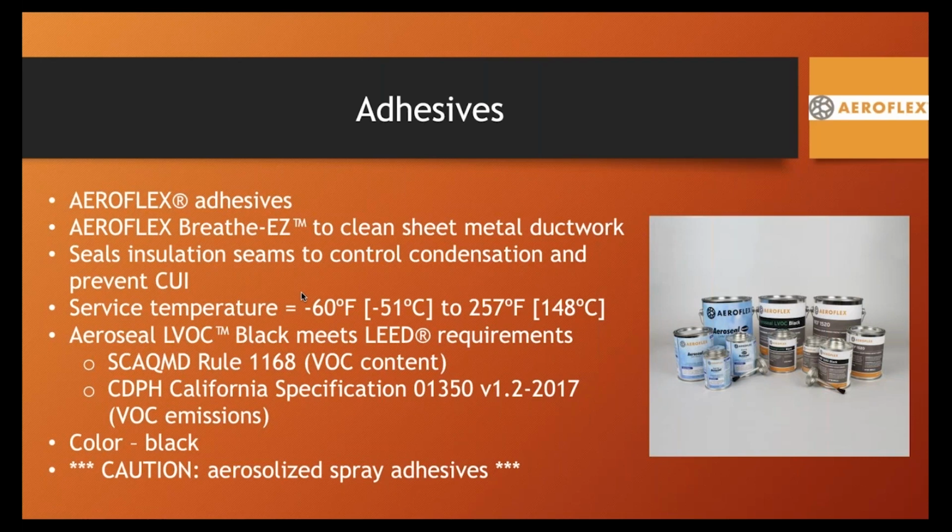have a favorite low VOC, typically spray adhesive, that they use for their fiberglass liner, and it's water-based. The problem with using water-based with elastomeric is that water gets trapped between two impervious surfaces, the sheet metal and the elastomeric liner. So it takes forever to dry.